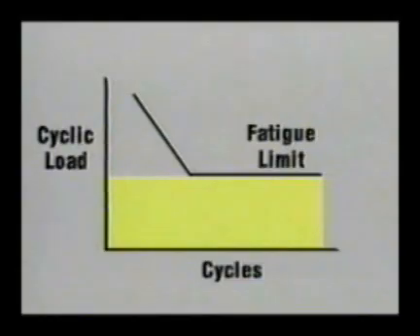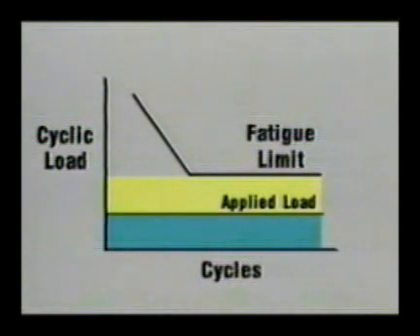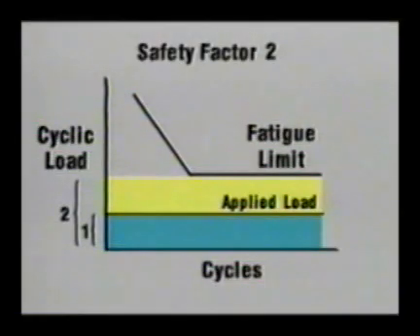Theoretically, if cyclic loading is kept below this fatigue limit, fracture should not occur. But some working conditions may vary from design expectations. Therefore, applied loads must be less than the fatigue limit. The comparison of fatigue limit to the applied load is called the design safety factor. If the fatigue limit is twice the applied load, the safety factor is 2.